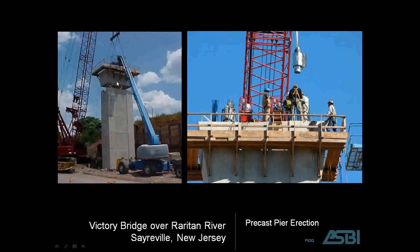Here we see the cap being placed on top of the pier. The last segment has a different detail. It has the anchorages in there for the post-tension tendons. On the right, the post-tension tendons have been installed and they're being stressed with these rams.